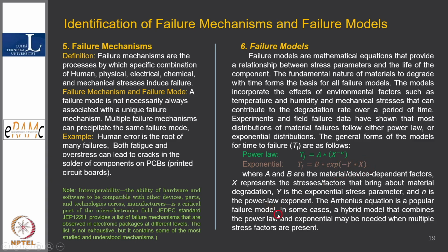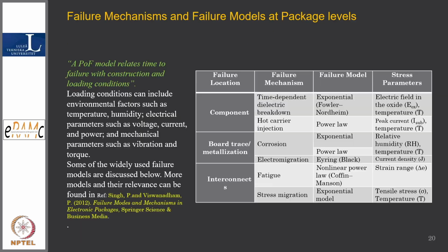So now we have talked about failure modes and models, and this becomes the subject of our discussion, because for failure mechanisms we have to give a failure model, and there are some models that are available, especially in electronics. A POF model relates time to failure to loading condition, environmental condition or operational condition.